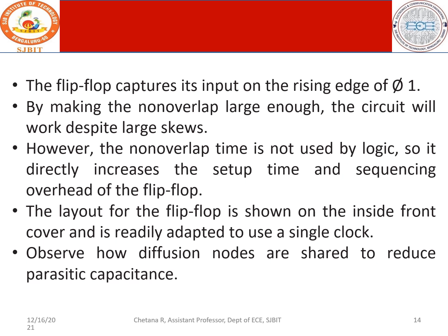So the flip-flop captures its input on the rising edge of phi 1, and we'll see this in the next slide. By making the non-overlap large enough, the circuit will work despite large skews. However, the non-overlap time is not used by logic, so it directly increases the setup time and sequencing overhead of the flip-flop. The layout for the flip-flop is shown on the inside front cover and is readily adapted to use a single clock. Observe how diffusion, we'll look into